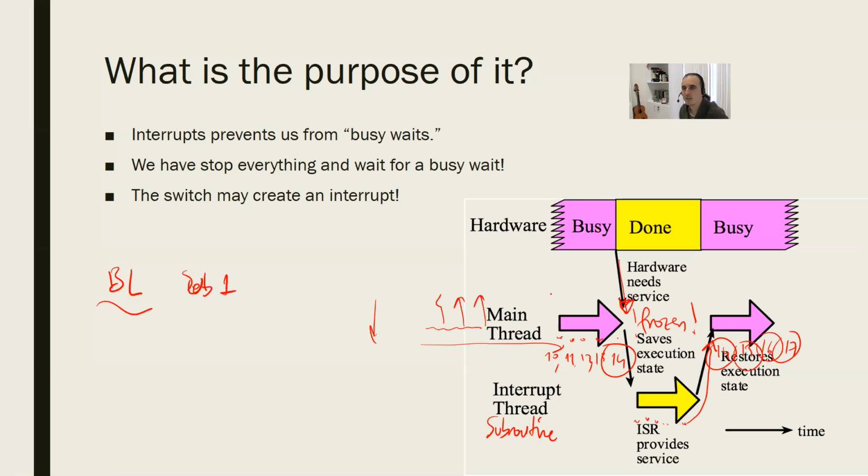So it is like if you are the main code and you jump to a subroutine, and if the subroutine changes a register, maybe you'll realize it because you made the code jump there. You said BL for a regular subroutine. But for an interrupt, if you're the main code, you don't realize it happens. It jumps there and you come back, nothing changes. Even the registers are not changed. It is like the time is frozen. So that's the theoretical difference between an interrupt subroutine and a regular subroutine.